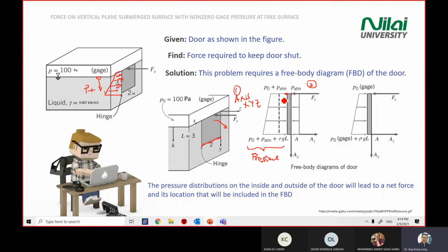Okay. Then after that we transform our free body diagram. We try to take out the repeated pressure. So in this case, atmospheric pressure was taken out because it's acting on both sides, so we don't need to consider it. We assume that this is open, so the water is exposed to atmospheric pressure, and here also atmospheric pressure.